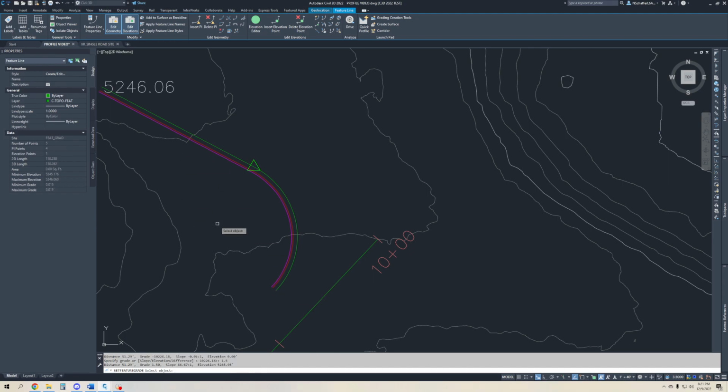And so now that I already selected my object to start, selected my points that I want to select, and I hit enter, select the grade, do all that stuff, it's a running command. So now it's wanting me to select an object again so that I could set the grades between 2 points for this additional line. So in this case, I don't want to do any more quite yet, so I'm just going to go ahead and hit enter.